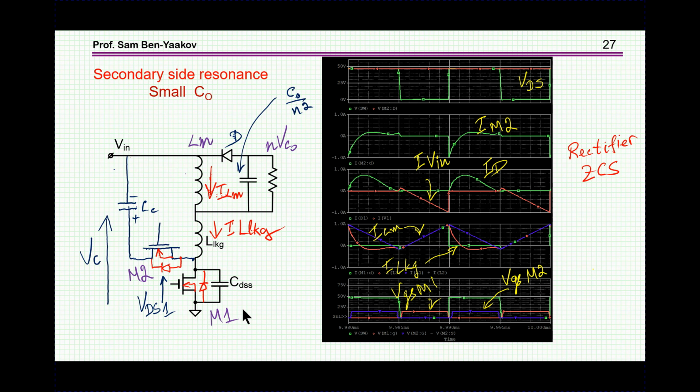So in fact, there's no way to operate an active clamp for a flyback converter without a dedicated controller. It's just impossible to build your own. It's just too complex a circuit for discrete components.